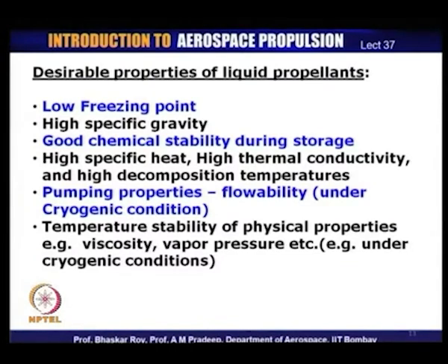Hence, it is necessary that the rocket fuel preserves its chemical stability and properties during storage. It should have high specific heat, high thermal conductivity for the heat to be conducted through its operation during the combustion, and high decomposition temperature. That means, it should not very quickly decompose before the actual combustion is initiated.